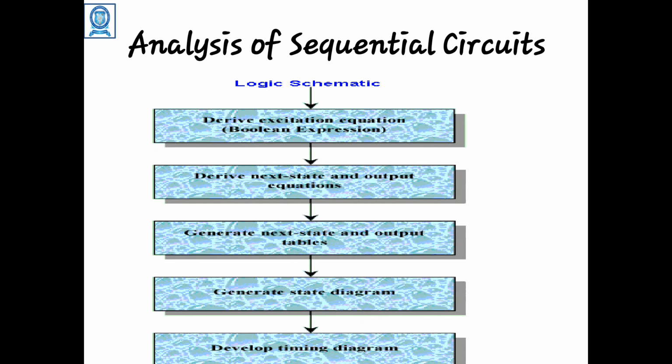As I said earlier, the combinational circuit is the one which is used to perform some operations. Half adder, half subtractor, full adder, full subtractor and comparator are all combinational circuits. They simply have an input state and an output state. There is no present state, there is no next state. Only for the given input, the output is generated. That is called a combinational circuit.